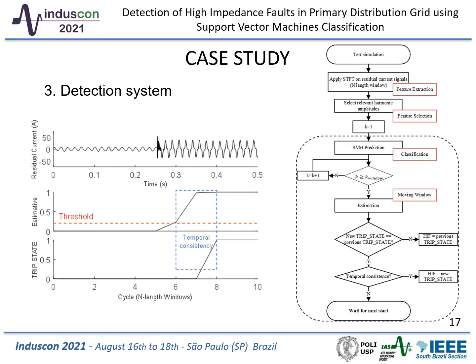To improve the optimization of the detection process, a sliding window strategy was used, where each analyzed window presents an overlap of 15% with respect to the previous one, to avoid spurious alarms due to the presence of short-term transients whose spectral characteristics may be similar to those present in HIFs. A temporal consistency of each detected event was verified. The flowchart on the right depicts the algorithm proposed for HIF detection, with the image on the left side representing an example of a correct detection.